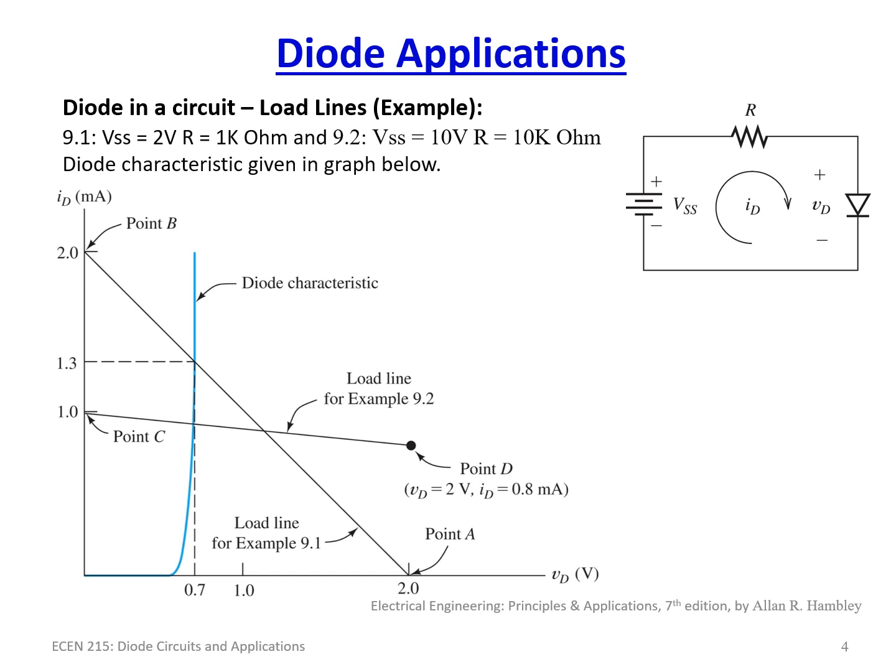Now looking at example 9.2 here, we're going to change. Now we're going to use 10 volts here, and this is going to be 10 kiloohms. This line is going to eventually intersect VD equal to 10 volts out here. But at 2 volts, by using y equals mx plus b, we're able to determine this point here at 2 volts. So that's how you determine this.